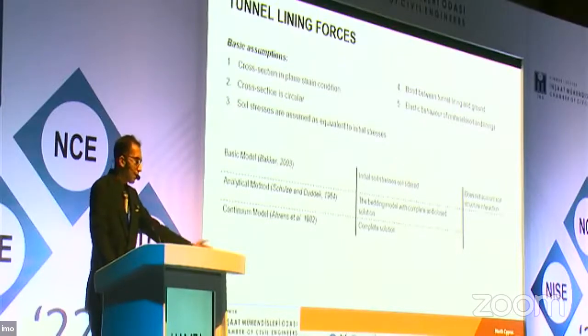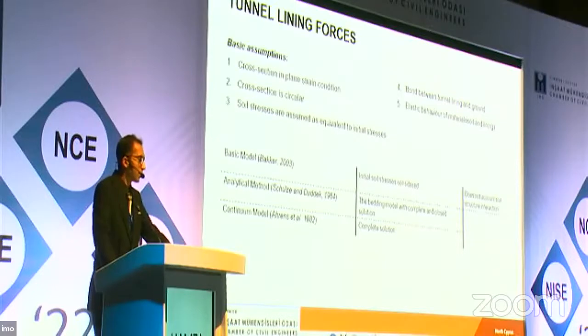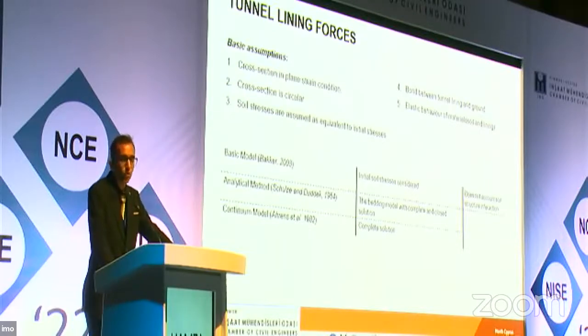So here, I will only specify 3 basic models. I have a basic model which is suggested by Baker in 2003, the analytical model, and the continuum method. In the basic model, only the initial stresses are considered, and the soil structure interaction is not considered. One of the drawbacks of that model is that it generally assumes very high axial forces and bending moment diagrams when it comes to the final design of the tunnel lining.